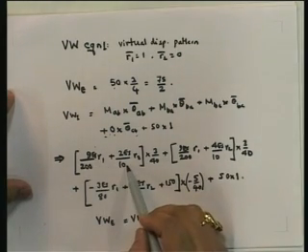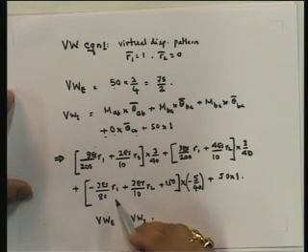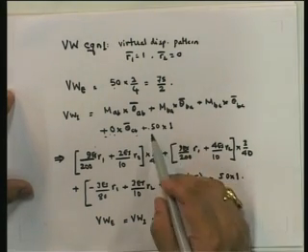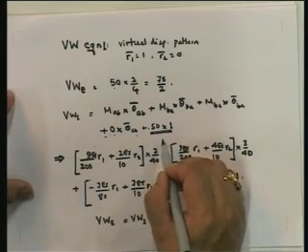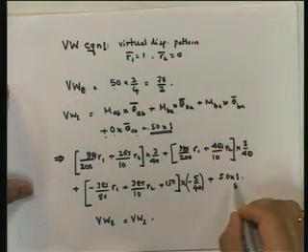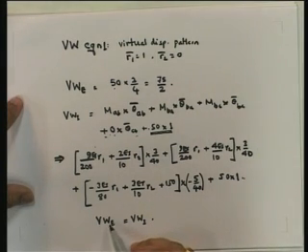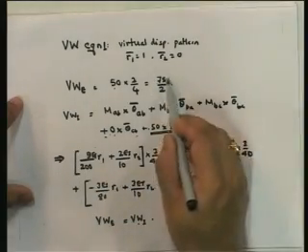So when I substitute MAB from the previous equation and multiply it by this, plus MBC multiplied by this, plus 50 into 1, this is the support reaction due to the member load of 100 kilonewtons. If you remember, I had told you that this is something you have to consider, and that is the support reaction. That goes up by 1, so therefore the virtual work is 1. Now the virtual work equation says virtual work external is equal to internal, so all we do is take this and equate it to this.